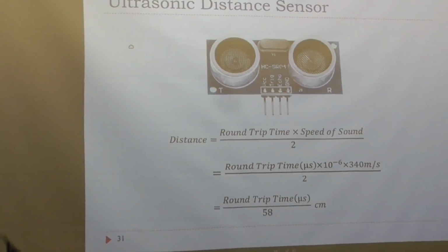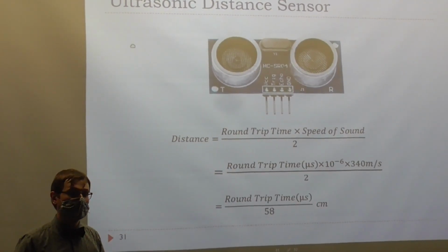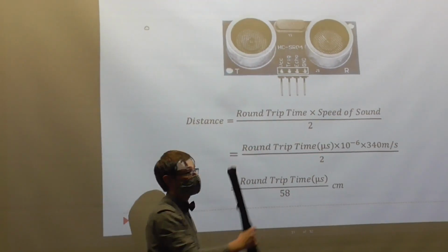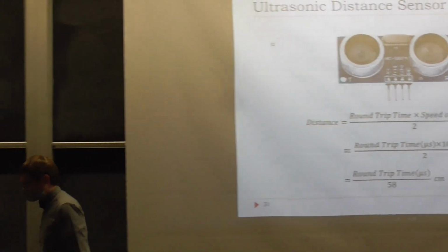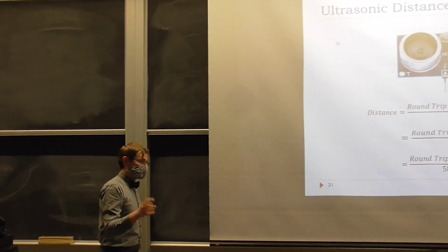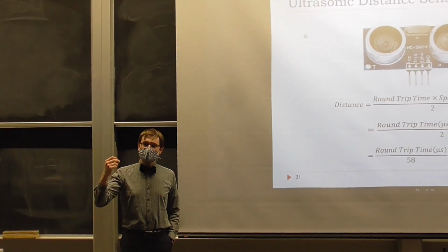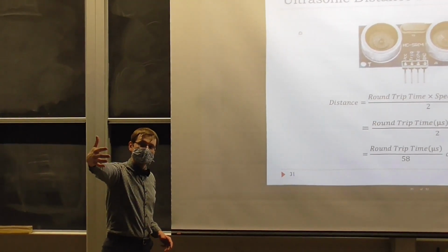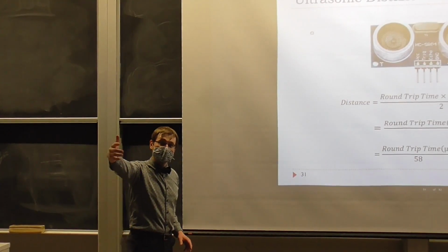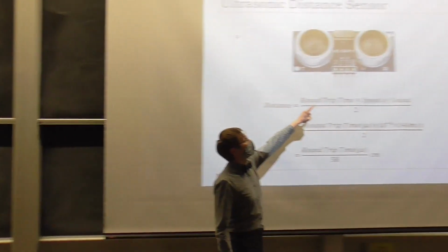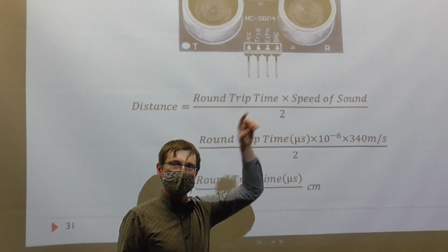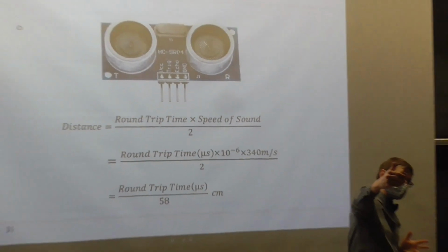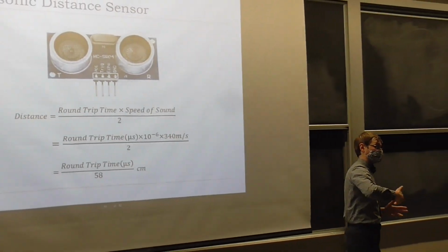This is an ultrasonic sensor, if you've never seen one before. They're pretty cool. You've got a transmitting and a receiving speaker on them. The way an ultrasonic sensor works, essentially, is the transmitting speaker produces ultrasonic sound. It bounces out into the room, reflects off of obstacles, and then the receiving microphone waits for the same frequency of sound to return to it.